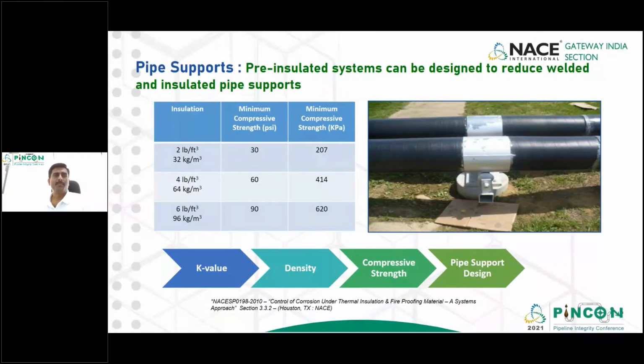Pipe supports. With a pre-insulated system having a good load-bearing capacity, the pipe supports can be designed to reduce welded and insulated pipe supports. Most of the supports or rest and guide shall be a cradle held from the outer weathering jacket as shown in the picture.